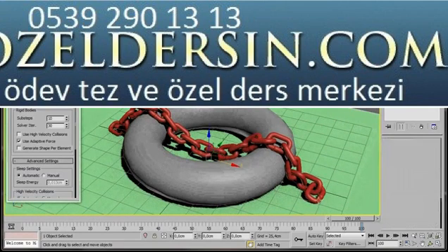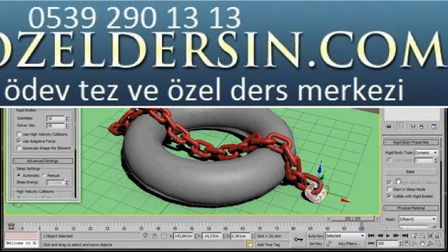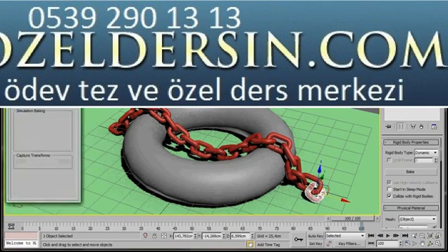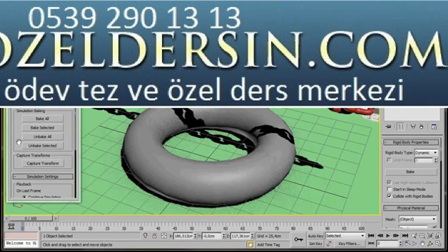This will open up the panel again. We can scroll up right to the top, and here we can find our bake button on the dynamic object. Also, we could go up to the simulation panel. Here we can find all the controls for playback and the simulation baking. We also have an Unbake All button. This will remove all the animated keyframes if we need to. Okay, let's go back and press reset, and then we'll drop down to the panel and we'll press Bake All.